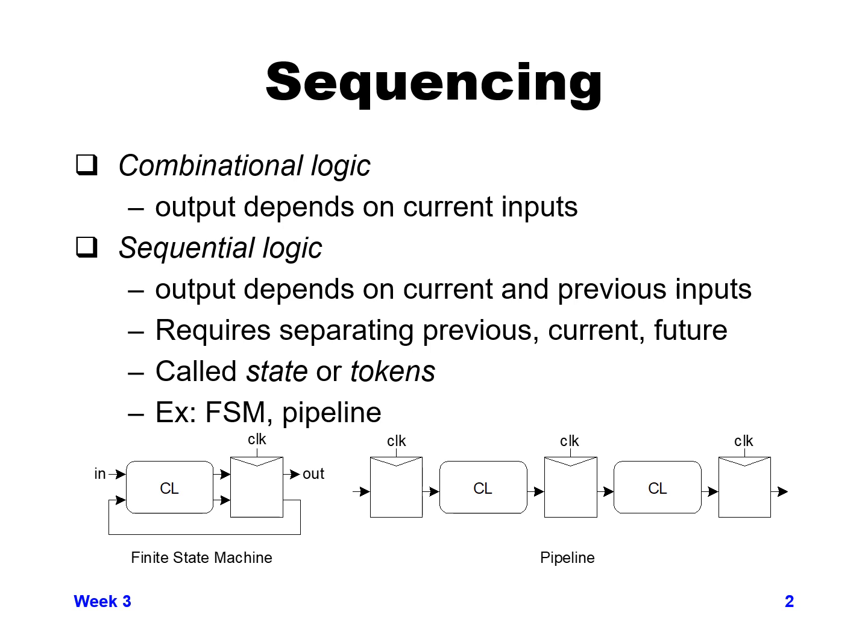For example, we might have a pipeline similar to what's shown below, where we have a sequential element that has a clock, and we only switch the output based on when the clock either is high or when the clock switches from low to high, depending on whether we're talking about a flop or a latch, which we've discussed in previous lectures.